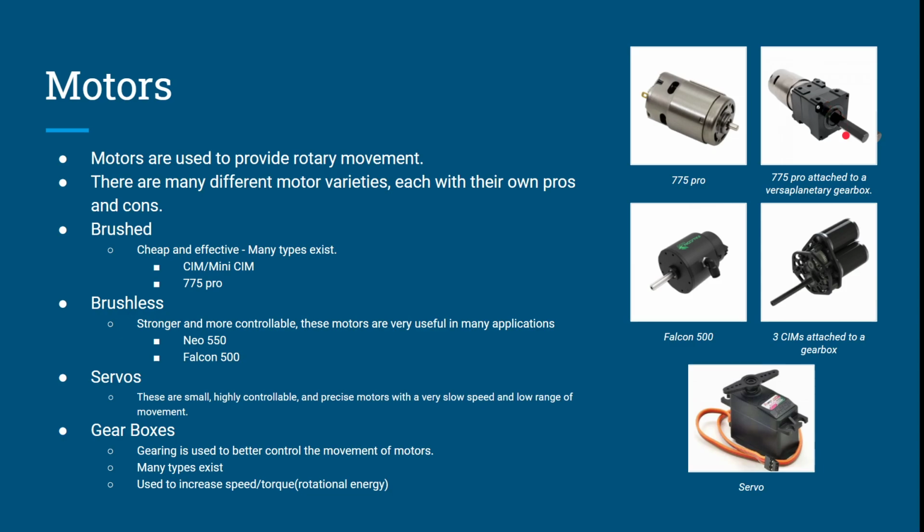You can see here that there's a gearbox. It's a planetary gearbox, like I talked about. So motor input goes in, gears reduce it. If it were a 2-to-1 reduction, you would have 2 rotations in for 1 rotation out, and you would have twice as much force coming out of your motor shaft. So theoretically, if you attached this to an arm with a weight on the end, you'd be able to lift twice as much weight with a 2-to-1 reduction. That's an oversimplification, but it's basically how it works. That's all you need to know for now.